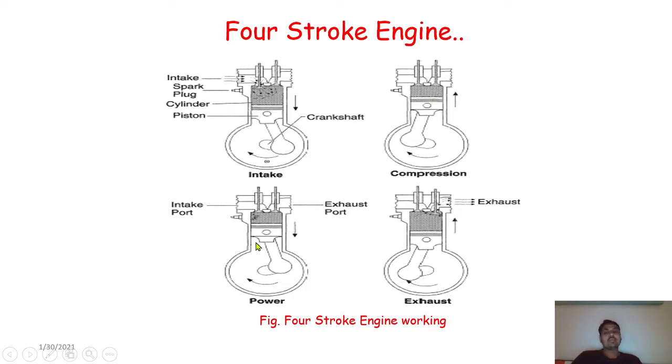The next process is the power or expansion stroke. What will happen during this process? This is again a very interesting and important one. Here is the spark plug. What happens, dear friends, in this case is that at the end of the compression stroke, when the piston reaches top dead center, at the same time the spark plug provides a spark inside the engine cylinder.